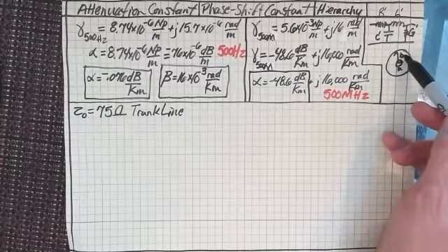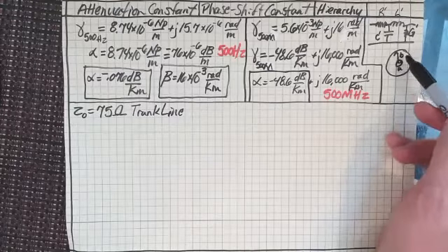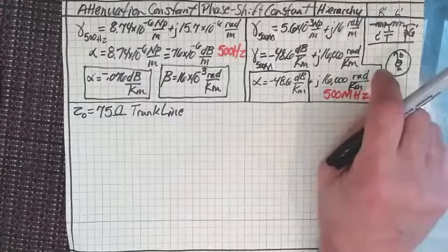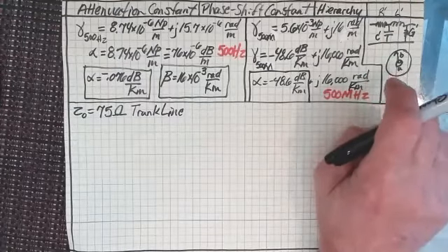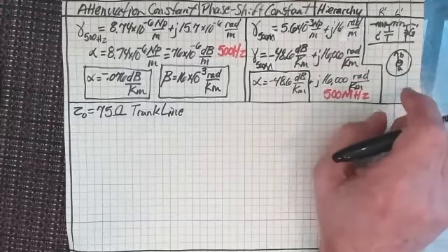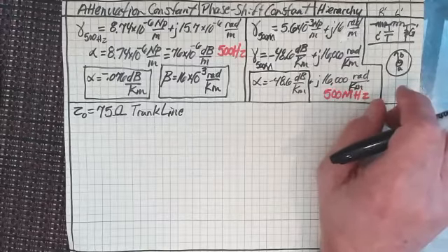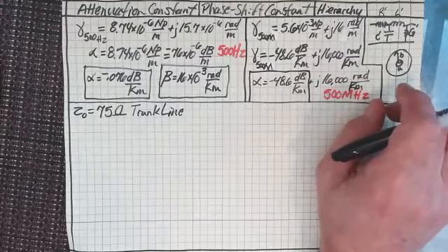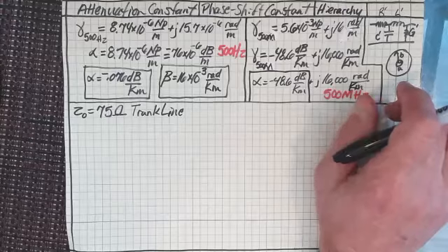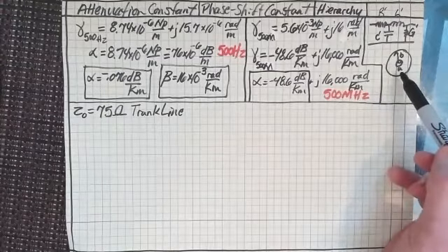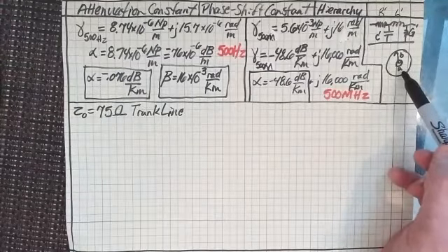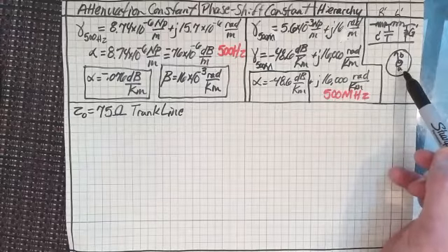Because most of the time we just use the ratio of B over A, and the natural log of B over A. But in some circumstances, like R prime, where we're looking at the ohms per meter, we don't, do we? We actually use the number. So it's not like you could put in the diameter there and it be equal to the radius, because we know the radius is 1/2 the diameter, so it wouldn't work out right, would it?